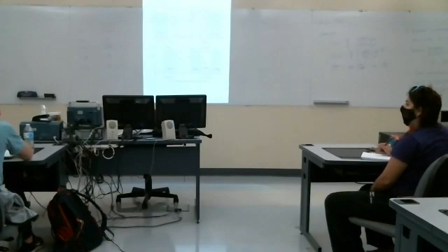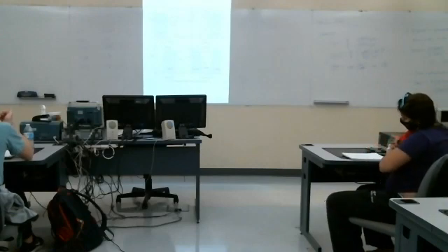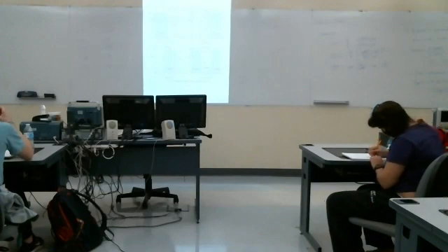A decade of frequency is a factor of 10. So a decade above 200 hertz is 2000 hertz. A decade above 2000 hertz is 20,000 hertz. A decade below 40 hertz is 4 hertz. That's the terminology. It's not adding or subtracting 10. It's multiplying or dividing by 10.